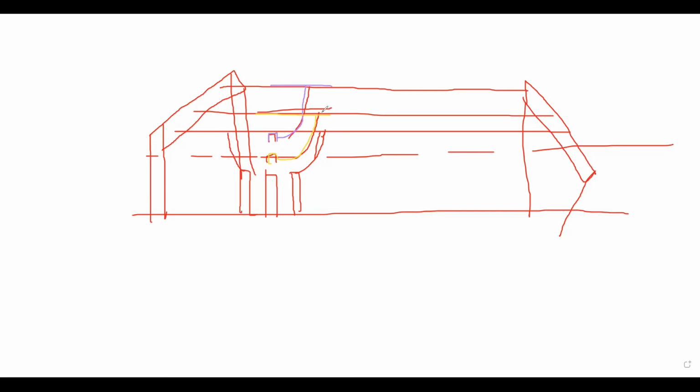Now, how can I connect this? With the connectors, with the clamps. And to run this conductor between the two structures, this is the phase. But the structure is a lattice structure. So if I connect it directly, it creates a short. So I have to provide some insulator material here to maintain phase to earth clearances.